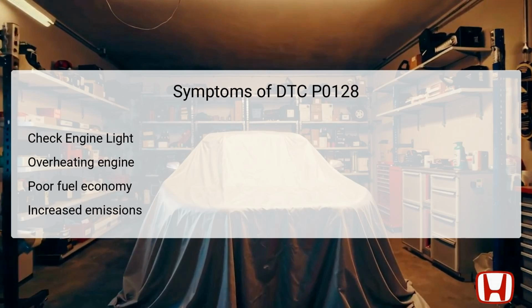Poor fuel economy is another potential issue, where the engine may run richer than needed as the ECU struggles to adjust to incorrect temperature readings. Lastly, increased emissions can occur due to incomplete combustion processes, emphasizing the importance of resolving this diagnostic trouble code.